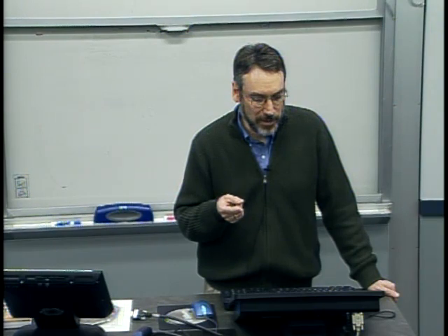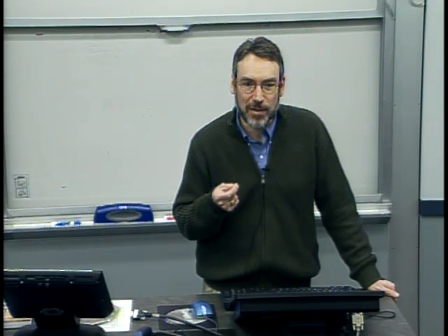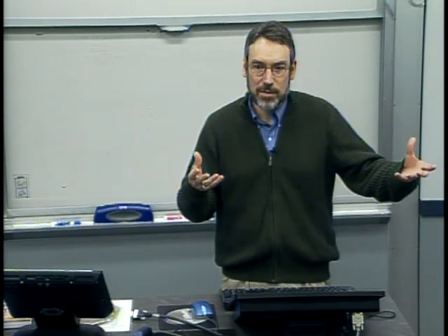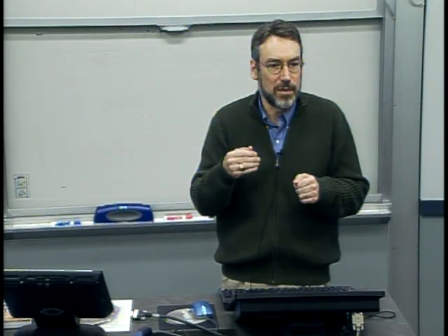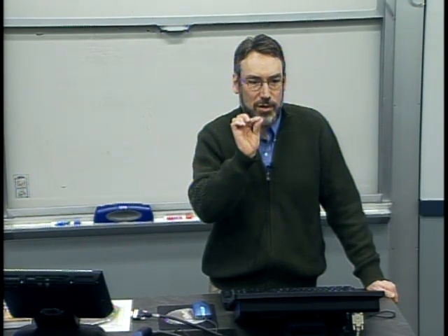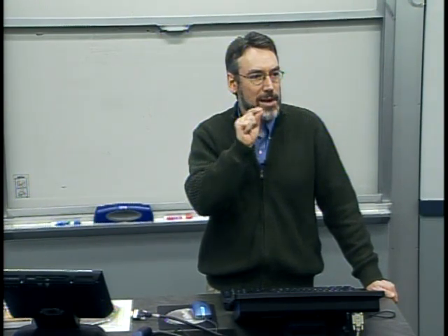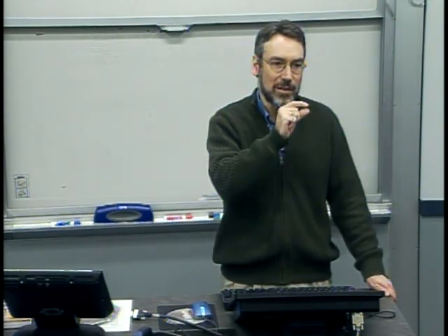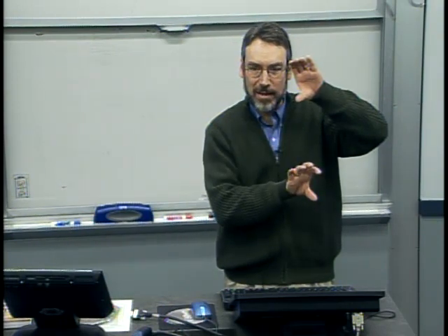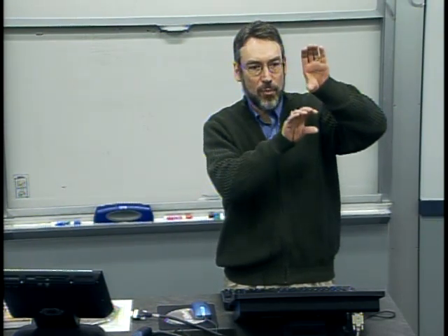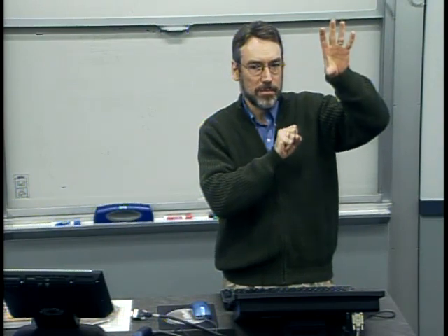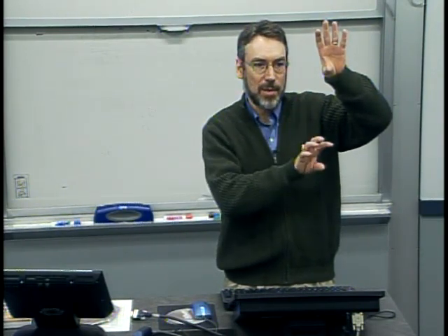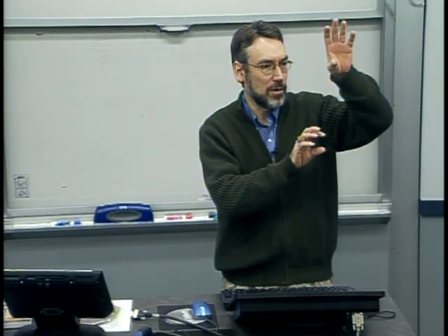And we'll talk about it a little bit later, but basically we're going to need insulating layers between conducting layers. One conducting layer being the silicon itself, the others, when we build multiple levels of wiring, we need insulators between them. But in particular, for the formation of that transistor, the creation of a very good, high-quality, very stable, well-controlled oxide insulating layer between the gate electrode and the silicon electrode was crucial. That forms basically a metal gate oxide semiconductor, or MOS, transistor structure.